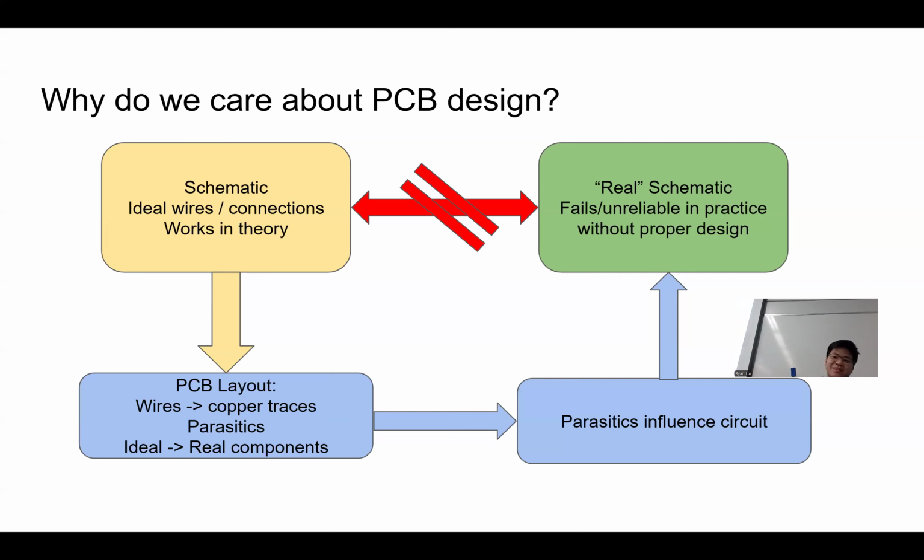The reason for that is that while you have the theory in one direction, in real life you unfortunately have what we call parasitics. Things like parallel connections, even your vias, all have tiny capacitances, inductances, and resistances. Your ideal wires actually have a couple milliohms of resistance.